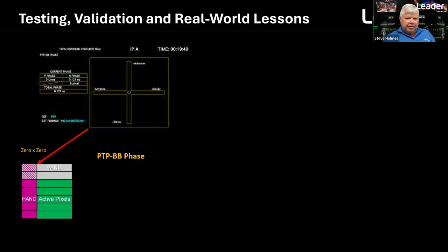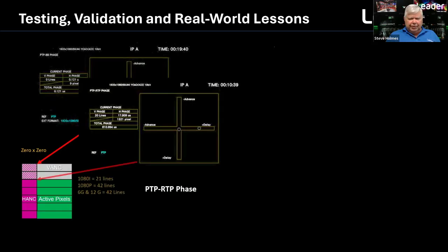And at some point, PTP may go out first, or video may go out first. And packets get in front of other packets, and packets get behind other packets. So there's always just a little wobble in what's happening. What we're really worried about is the data that's inside of that to actually remove that little bit of wobble. But your horizontal offset, you are going to see just a little bit of movement in it.